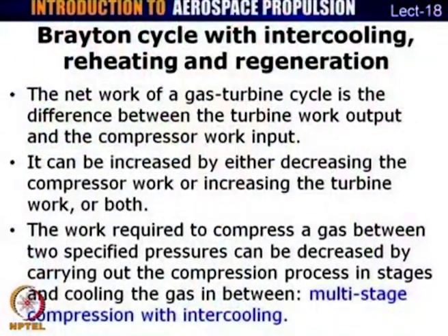Now, there are other methods of increasing the efficiency or work output of a cycle as well. One such method is what is known as intercooling, and the other method we shall discuss is reheating. Now, intercooling concerns the compression process of a cycle. Reheating concerns the expansion part of the cycle.